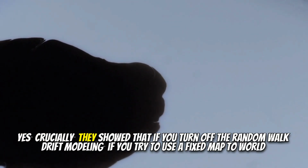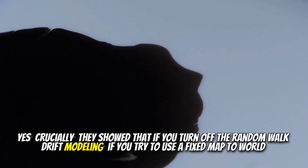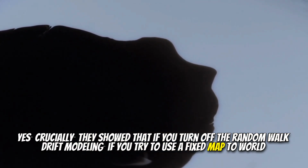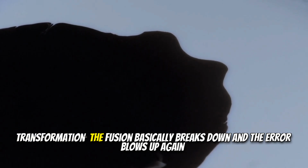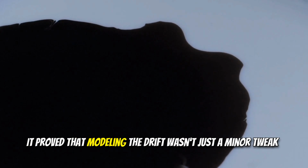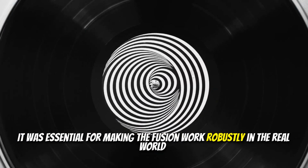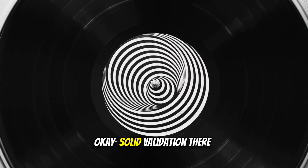Yes, crucially, they showed that if you turn off the random walk drift modeling, if you try to use a fixed map-to-world transformation, the fusion basically breaks down and the error blows up again. It proved that modeling the drift wasn't just a minor tweak, it was essential for making the fusion work robustly in the real world. Okay, solid validation there.